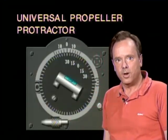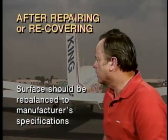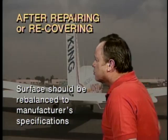Now let's assume as a mechanic you've done some work on the rudder of an aircraft. Maybe you've repaired it or recovered it. What should you do next? And the answer is you should balance the control surface according to the manufacturer's specifications, because if it's not properly rebalanced, you could have control system flutter.